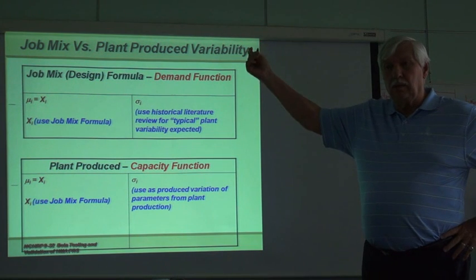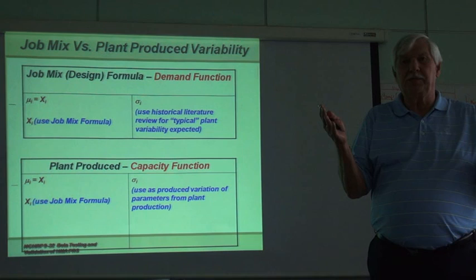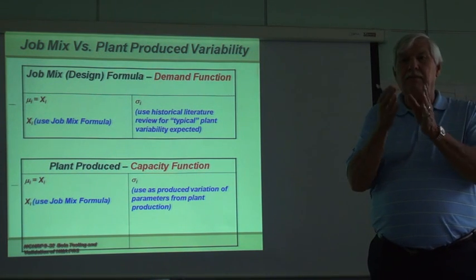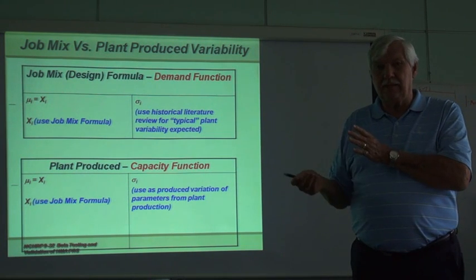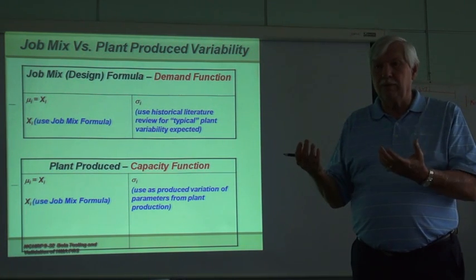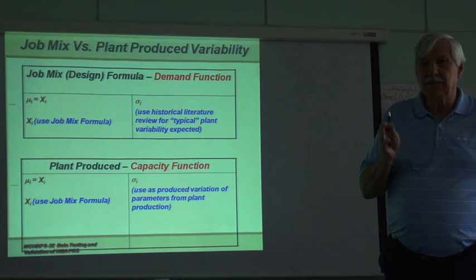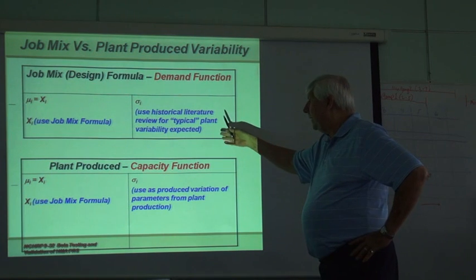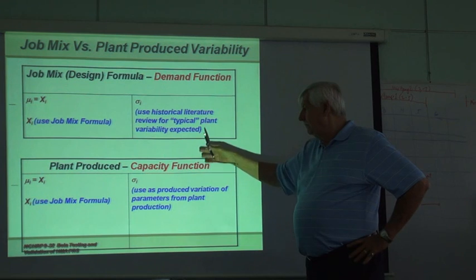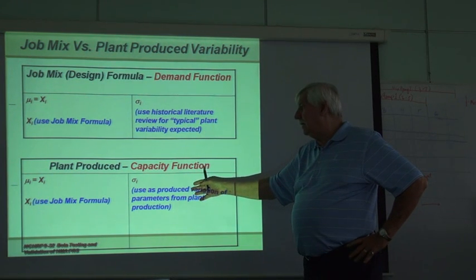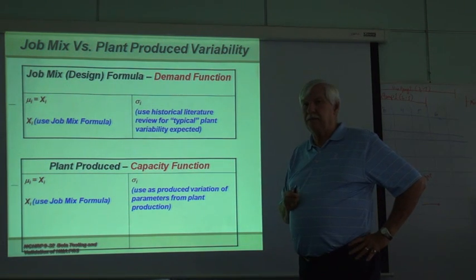Statistically, you can pool all the projects. In other words, if I have 20 projects over X years, I can take the individual standard deviations of asphalt content in every project. And statistically, I can pool the variances to come up with what is the best estimate for Costa Rica. So what I'm getting at is this information, either you have or you have the database for it. Okay, when we talk about here, the plant produced, think about what the contractor is going to do.